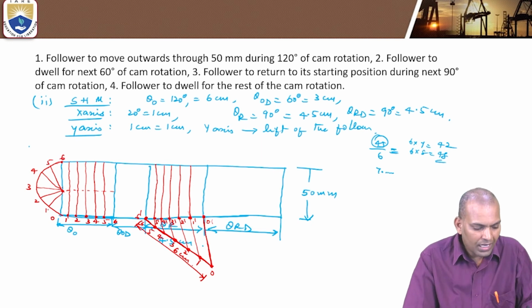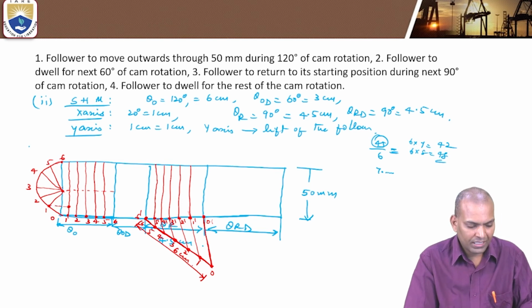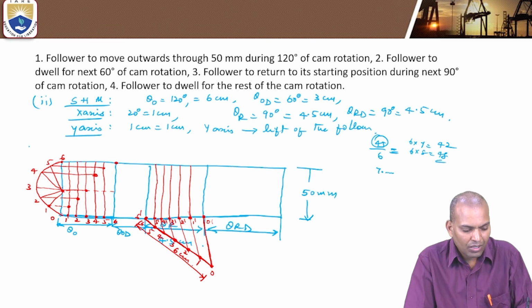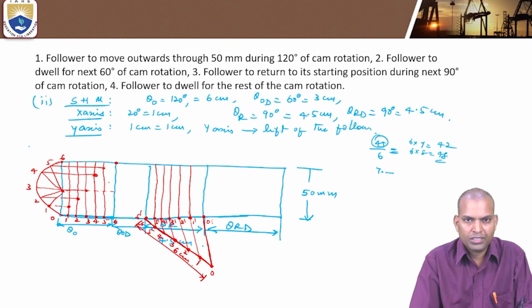Now draw horizontal lines from each angular division point of the semicircle, passing through the vertical lines. One intersects at the 1 vertical line, then draw a horizontal line for 2 and 2. Next 3 and 3, 4 with 4, the 5th division point with the 5th vertical line, and the 6th division point with the 6. Join all these points with a smooth curve.